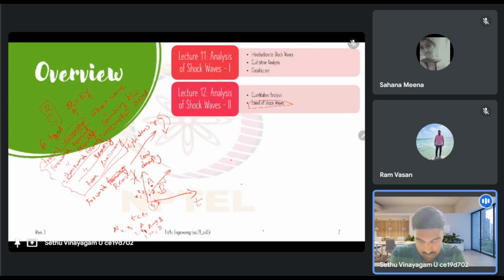So how do we determine this? If you have the QK fundamental diagram, generally we have a shape like this, right? When you have two traffic states, again, as I said, a traffic state is nothing but a unique combination. So if I say this particular point A, it has a particular flow value QA and a particular density value KA, right?